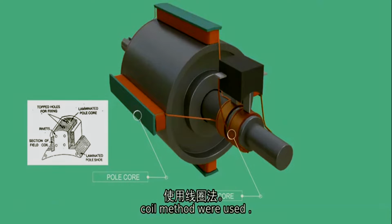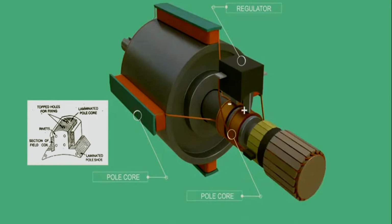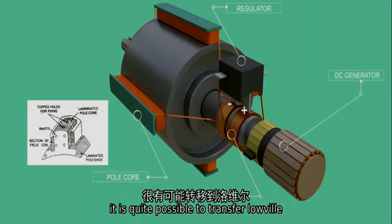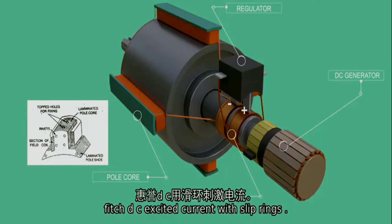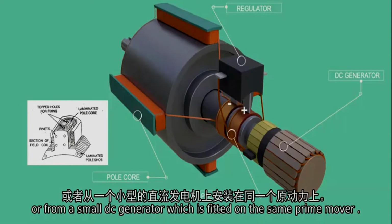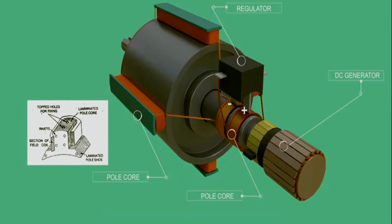If rotating coil method were used, slip rings have to fit it along with the armature coils in order to collect electricity. But transferring such high voltage electricity with slip ring is rather impractical. It is quite possible to transfer low voltage DC excite current with slip rings. This DC current is supplied either from an external source or from a small DC generator which is fitted on the same prime mover. Such alternators are called self-excited.